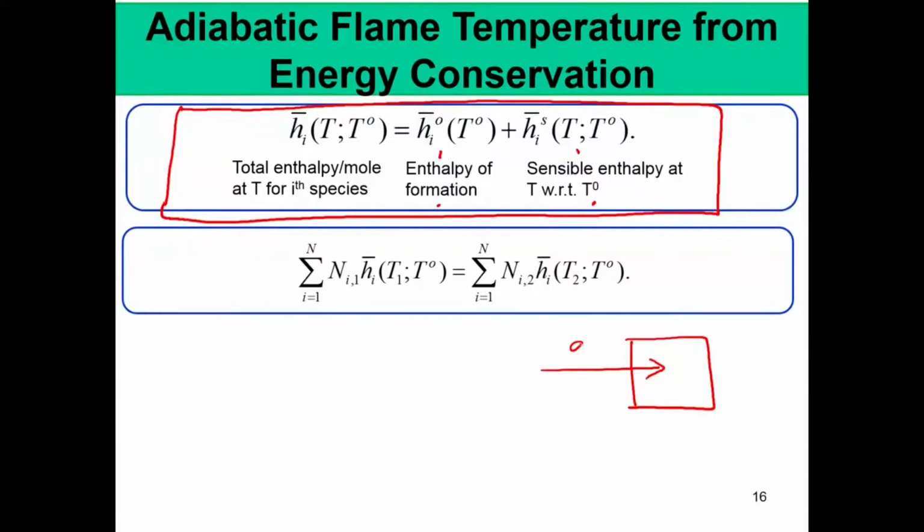Please understand this: when you model combustion in a given engine or something, you cannot model it like an energy crossing the system boundaries. It is basically a rearrangement of the enthalpy from the heat of formation to the sensible enthalpy part.